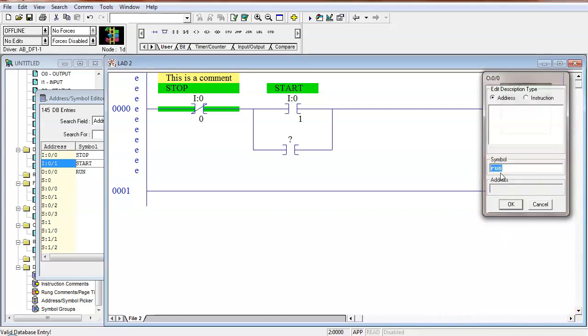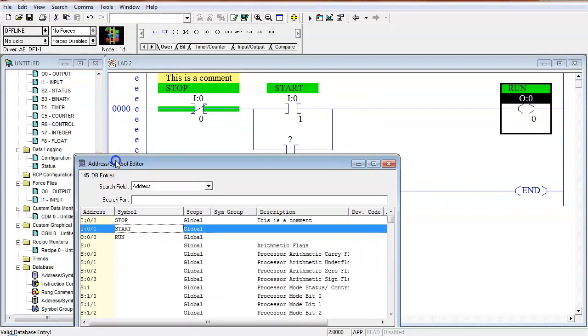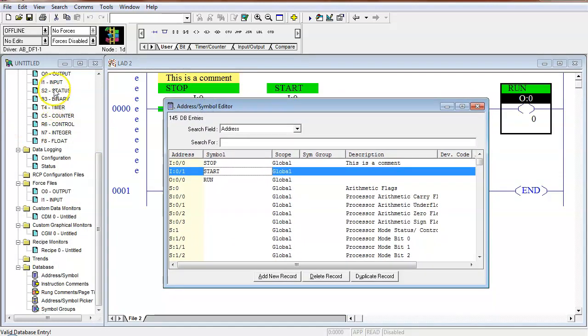Okay. We have to identify the portions of the command, so we'll look at the actual addressing scheme. What I've done is I've assigned this over here to the data. Inputs are actually file 1. Right now we're not having to do that, because the inputs are internal. So if you say I, it knows to use file 1.